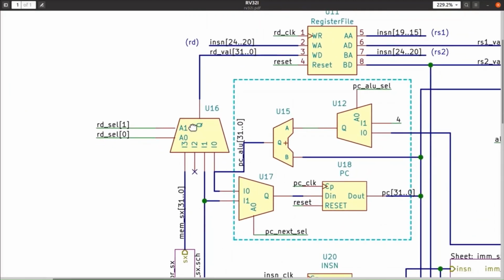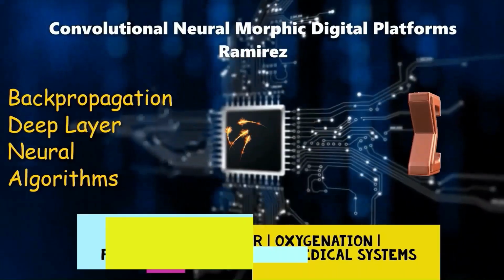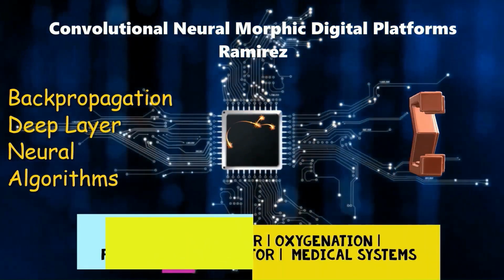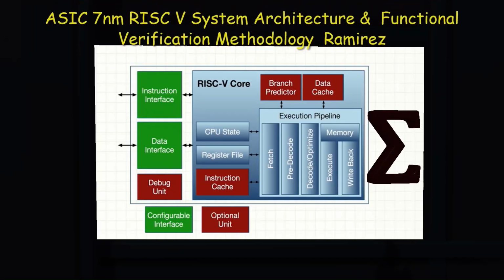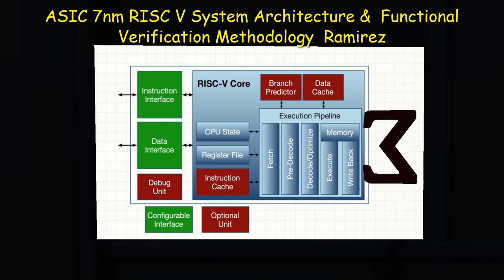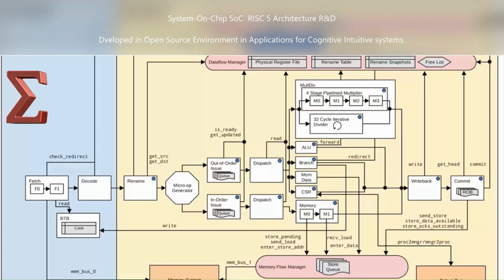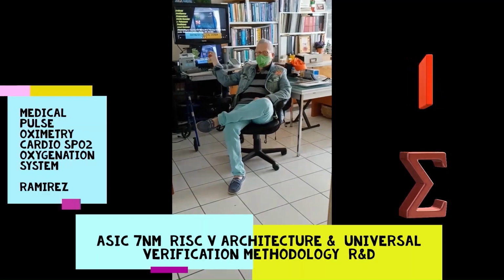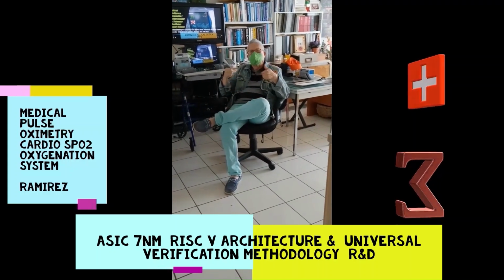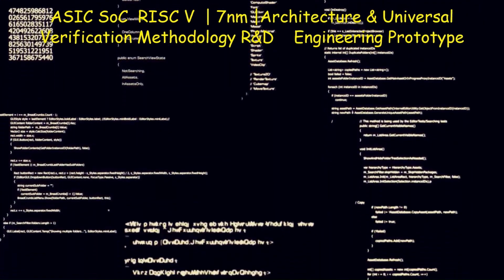Then top level test setup. For all the top level tests, you will also need a RISC-V compiler to build the firmware. You will also need to install the management core for the Caravel ASIC submission wrapper. This is done automatically by following the PDK installation instructions.